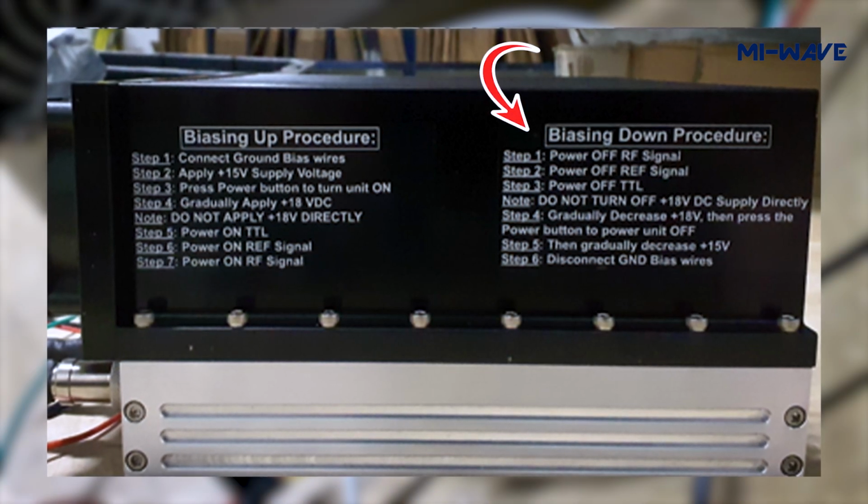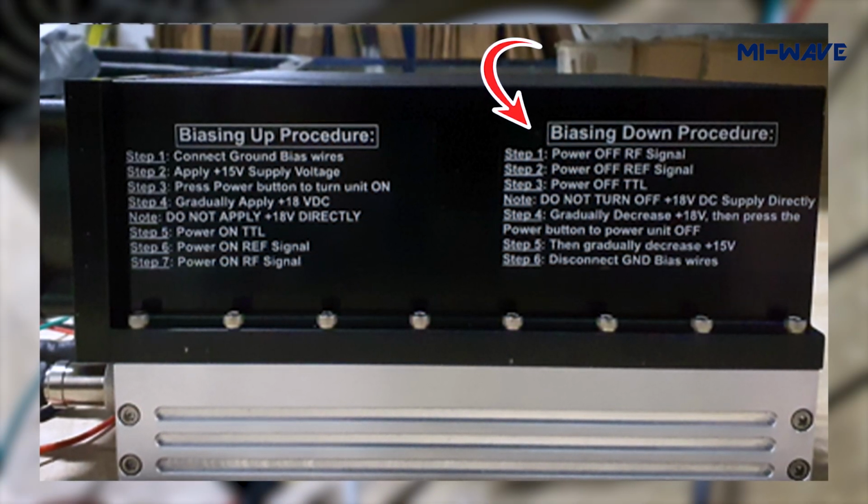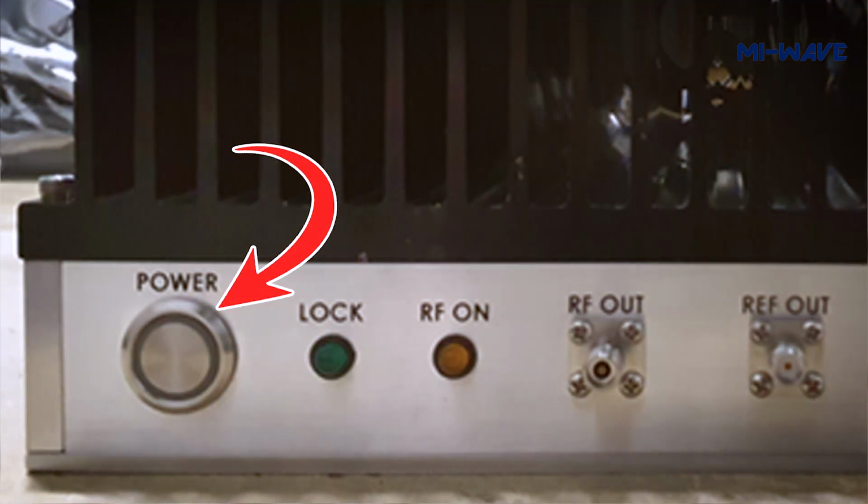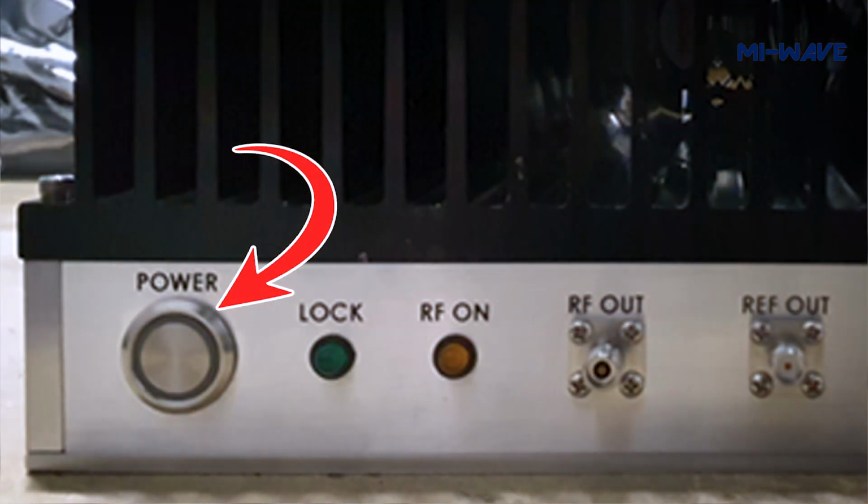Always follow the bias down sequence provided on the synthesizer label and in the datasheet. Before disconnecting any cables or turning off the power supplies, first turn off the synthesizer using the power button. Next, disconnect any equipment connected to the RF out port. In your setup, this port will have the antenna assembly, transition, and adapters connected.